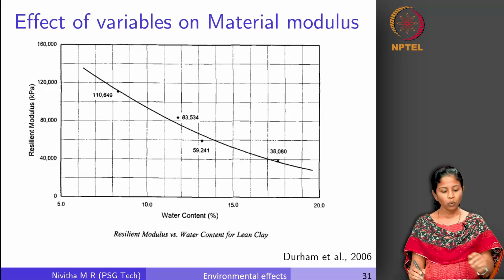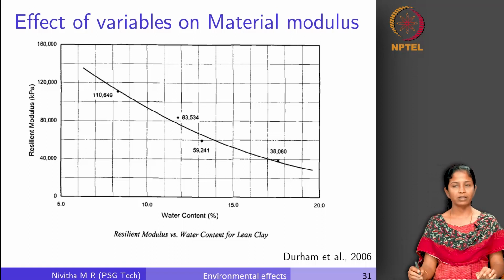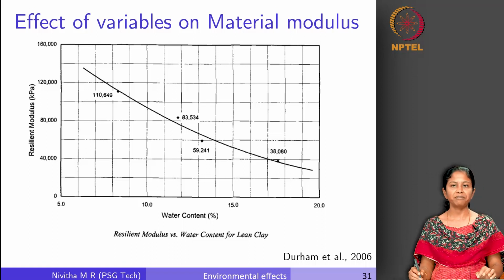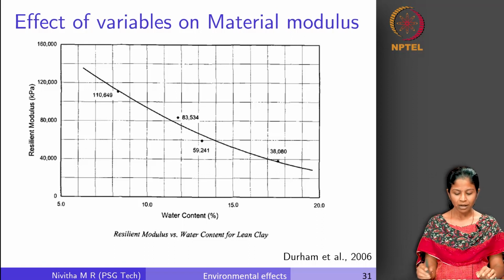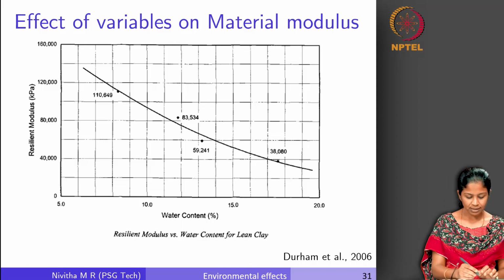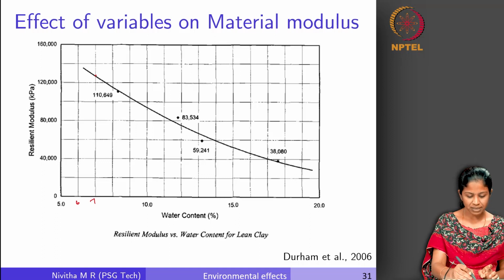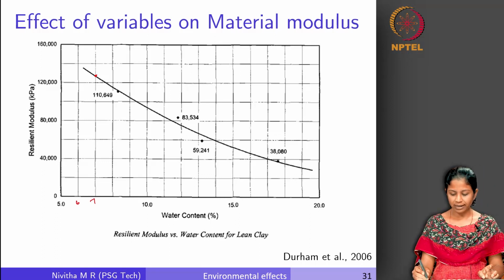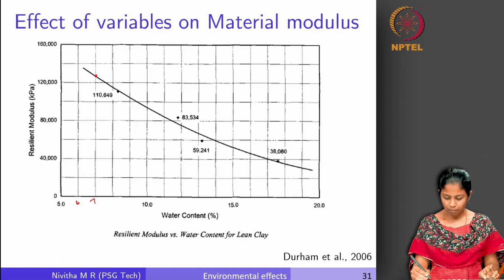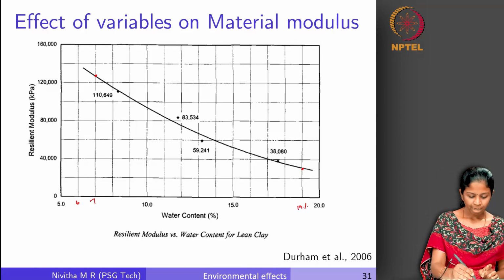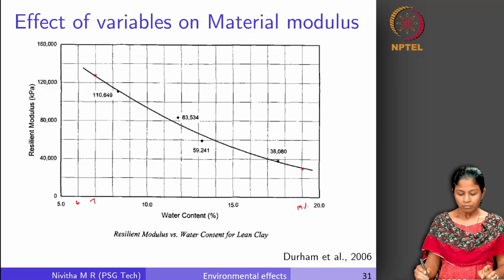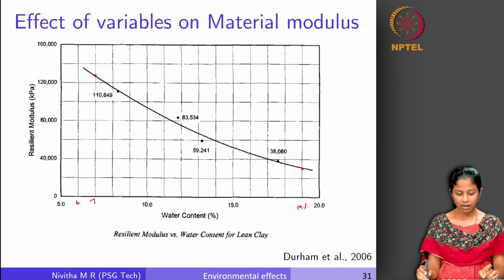Now, let us see what is the influence of water content on resilient modulus. Ultimately, that is what we are interested in quantifying. As the water content increases from 7% here, up to 19%, we can see there is a substantial variation in resilient modulus.